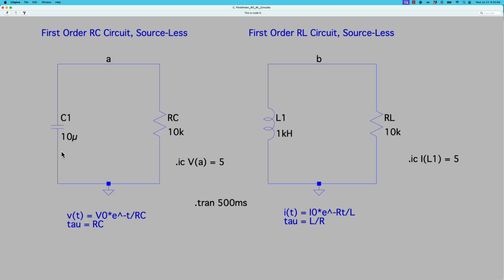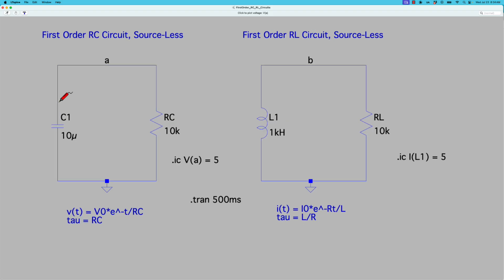The capacitor acts as a temporary battery, and it is something that can separate the positive and negative charges on two different plates. However, it also acts like a spring. So when you have a source connected to the RC circuit and you disconnect from the voltage source, the capacitor acts as a temporary voltage battery, and it is able to send current back into this resistor until it depletes to zero.